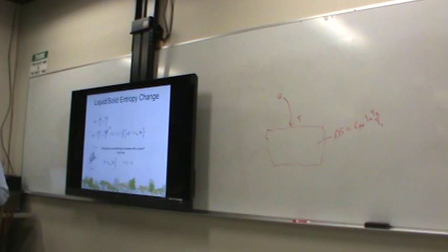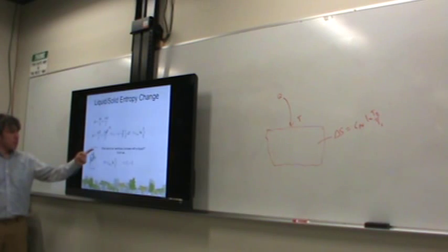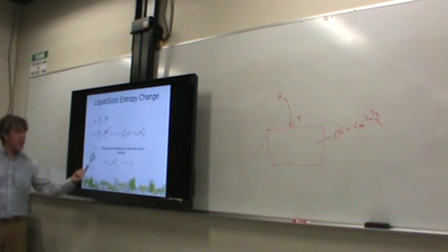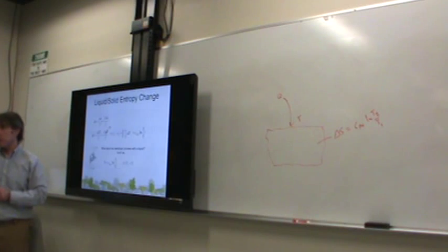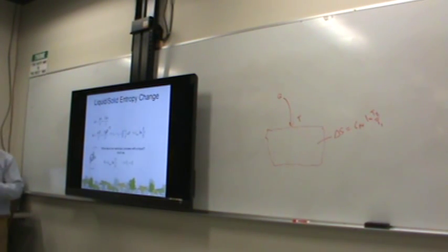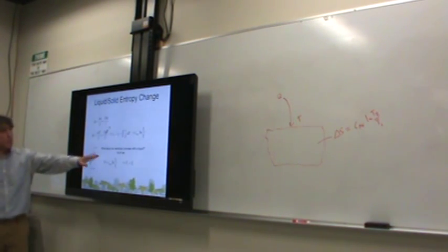He was testing some of the pumps they made. Now, if you were an engineer and you had to test pumps and you wanted to compare two pumps to each other, how could you do it? Well, you might look at the temperature change of the fluid as it flows through the two pumps. The one that has the lower temperature change is the better pump because it's closer to an isentropic pump. It has less internal friction, less turbulence generated, okay, so it's more reversible. Make sense? So this stuff does have practical application.